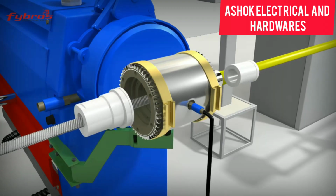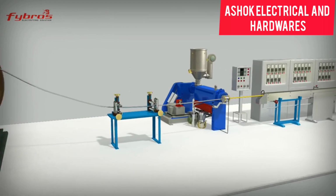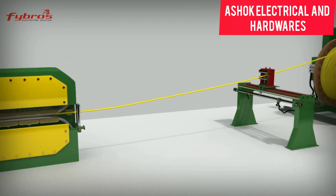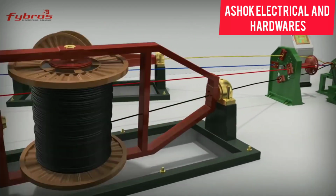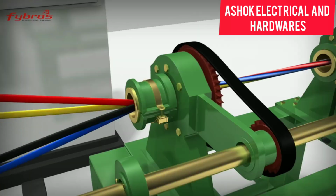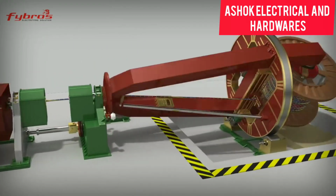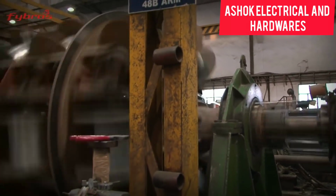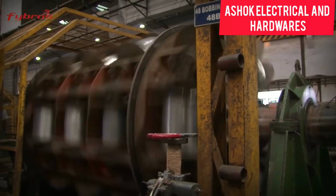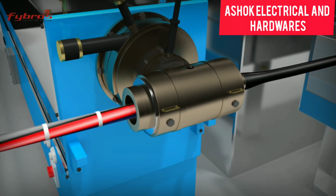We use self-cured XLPE or PVC compound for insulation of core copper or aluminium wire on an extrusion line as per required specification through the modern drum twist machine. All rewound cores are then laid together to form a cable as per specified design. Then, another layer as inner sheath is added by extrusion line.